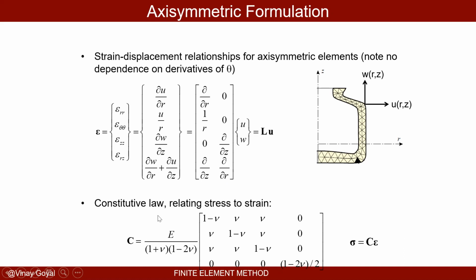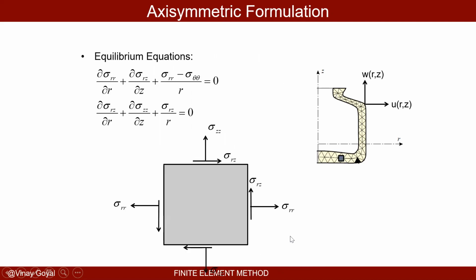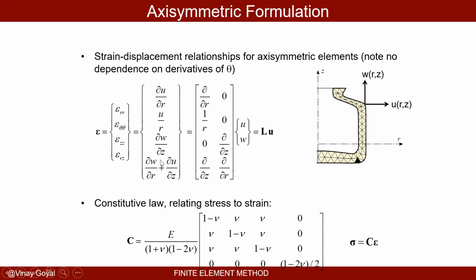The constitutive law will relate stress to strain in this manner. That's the constitutive law that we derived for plane strain elements, and it makes sense to use it here for the axisymmetric formulation because the circumferential coordinate is basically infinite. I can keep going around and around. So this constitutive law is more similar to the plane strain formulation. These strain deflection relationships may not be familiar to you, but they're derived in more advanced theories. They're also derived in my book, but for now, we're just going to provide those relationships instead.